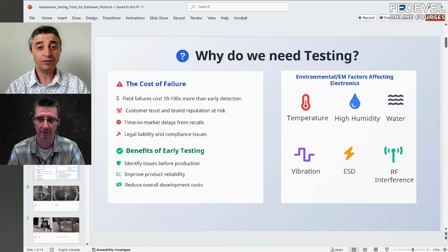If a product or design needs to work in an environment that is really humid, then you need to know: do you need to add conformal coating, for example? Or if there's an environment with sour gas, high corrosion or exposure to salt. There might be other situations where your product might be subject to high temperature.